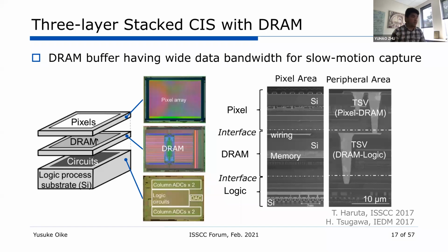What they did is have, I think, 1 gigabit of DRAM inside the sensor that buffers the huge amount of frames while the camera is capturing the scene. Once you finish capturing, the frames are then transmitted outside the sensor. Okay, I see. Thank you. So this particular sensor is dedicated to slow motion capture, but they also have some computation logic here. It certainly does not have to be DRAM. Meta's recent ISSCC paper, I think, used an SRAM.